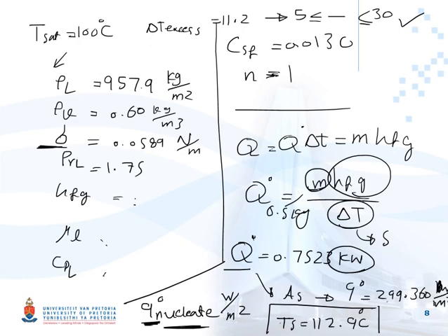First you calculate the delta T excess. If you can't, as I mentioned, first you assume a value. After that, you calculate the T surface, and at the end you compare it and examine if your first assumption was right or wrong.